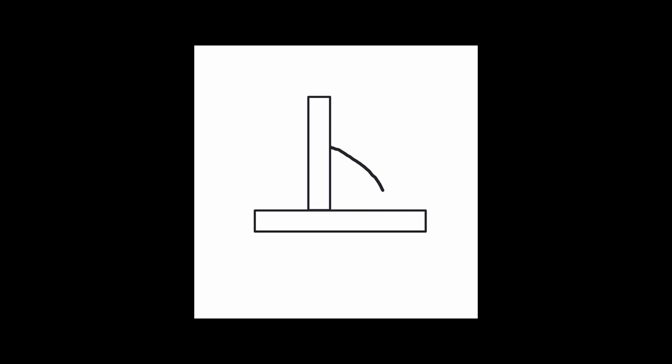So as we start talking about the throat of the weld, we need to understand that the fillet weld extends past the surface. This is what we call penetration. And I'm going to go ahead and draw that out for you. So understanding that the weld penetrates past the surface is going to make a couple of these variations of a throat a little easier to understand.